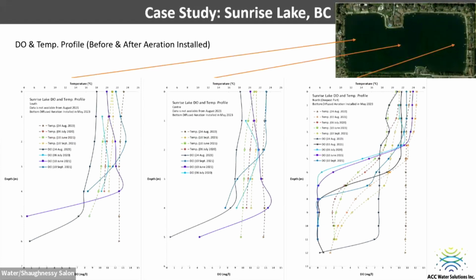If you're dealing with a bigger raw water body, whether it be a lake or a raw water reservoir, invest in the data. If you don't invest in collecting the data, then if you're talking aeration, you have at best a 50-50 chance of it doing what you want it to do, because it'll be very hard to design and size it without good bathymetric mapping, good DO and temperature profiles, decent water chemistry, and at the ultimate end, sediment coring and phosphorus fractionation data.